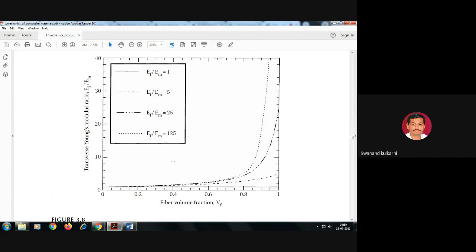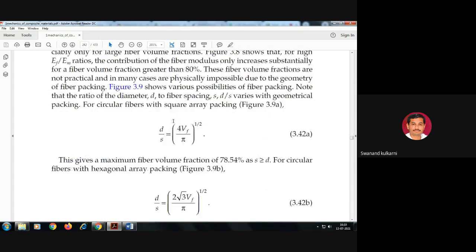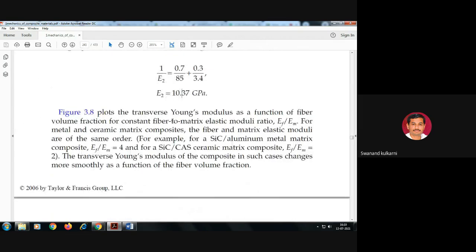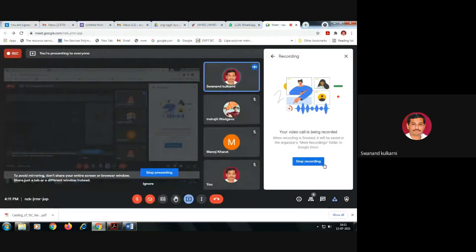So that's why we can't say this is an isotropic material, and this isotropy changes to orthotropy in this kind of materials. Is it okay? So this Young's modulus, the same figure which was previously drawn, here it is also plotted in order to find this. Is it okay? So with this strength of materials approach to identify the Young's modulus in lateral and longitudinal direction, that much part is over here. So anybody, any doubts with this?